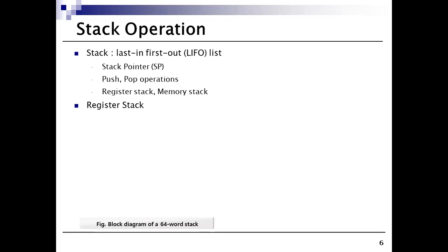Okay. So a stack in terms of a computer is also a kind of storage device, mainly used for storing information in such a manner that it uses the last in, first out principle. When I come to a stack in a digital computer, we require an address register, which can be count only, which holds the address of the stack, which we call the stack pointer.